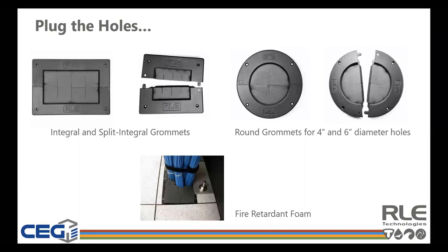So using blanking panels and racks, grommets and/or fire retardant foam and floor cutouts and in between the racks and floor, and sometimes baffling under the floor, can still contribute to more efficient cooling. So this becomes even more critical when using aisle containment. Because if air can escape the contained aisle through these types of openings, you're limiting the effectiveness of the containment and decreasing your cooling efficiency. These measures are cost-effective and easy to implement in existing or new data centers.